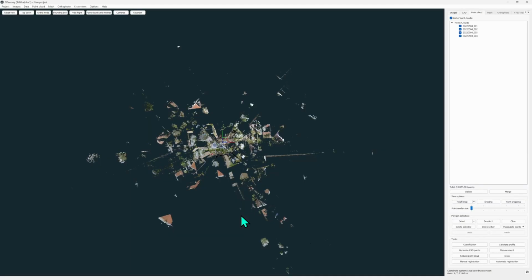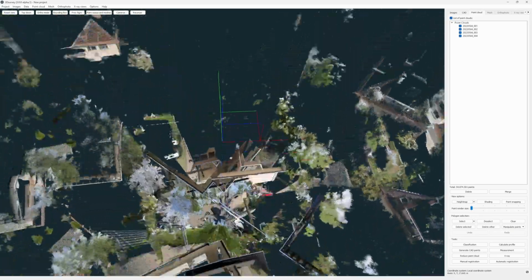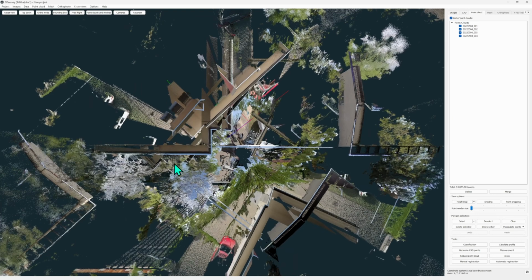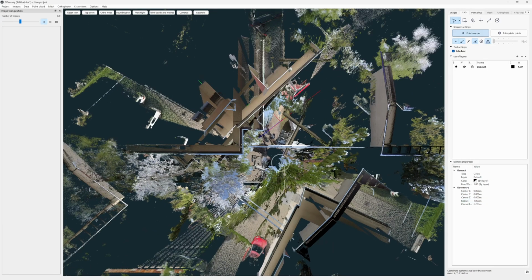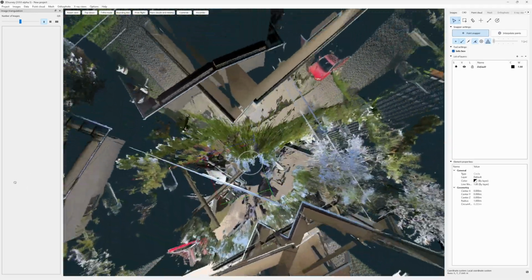You'll notice they all fall into the same coordinate origin. They were taken on different spots, but since the scanner doesn't record telemetry, they have no info about coordinates or rotation. That's why they end up on 000 coordinate. To illustrate that, we'll quickly draw a circle here and give it those coordinates. Okay, so this is the point where all the standing points fall to.